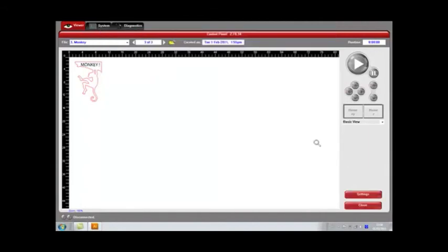Right, as I was talking about, because it's demonstration purposes and I'm doing this on my laptop, it shows that the laser cutter is disconnected. On the proper computer, this will show up as connected, idle, and up here, this will be green. And also down here, we're allowed to use our basic view, focus view, estimated view, and relocate. The one that we use on here a lot will be focus view, so that allows us to basically click, and where we click, the laser cutter will move within the physical space to that area, so therefore we can align up pieces and so on, like so.